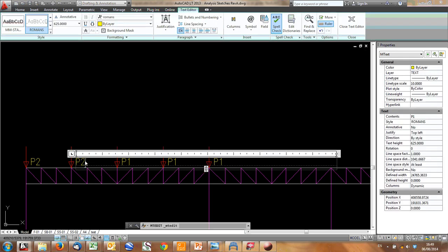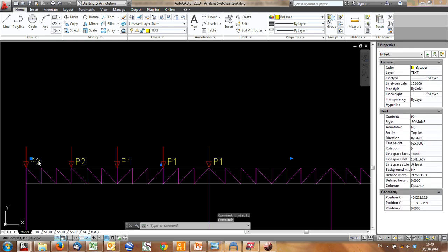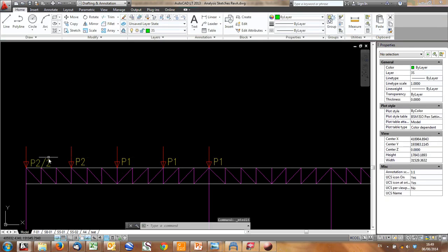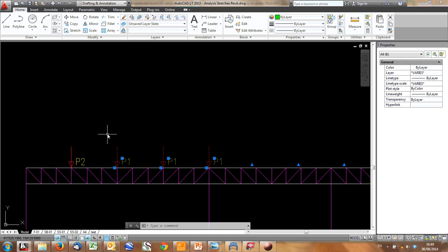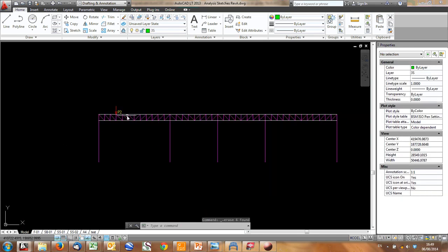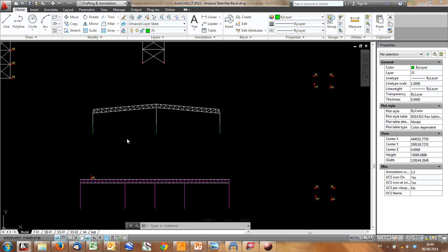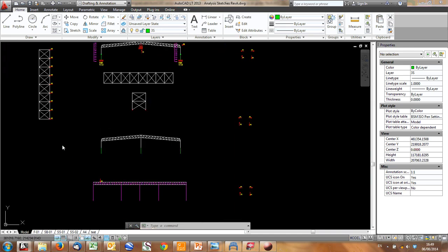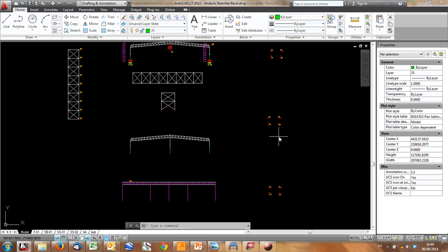I'll go through just to show you how those apply. Well, the end one actually would often be P2 over 2 if you halve it, or if it's a rafter, it would be even less than that. But we'll come back and have a look at this force now. Calculate that, but all the rest of these will obviously be P2. The reactions though, now what horizontal forces would be applied to this? Because we've applied wind load naught, our load combination when wind comes across the structure.